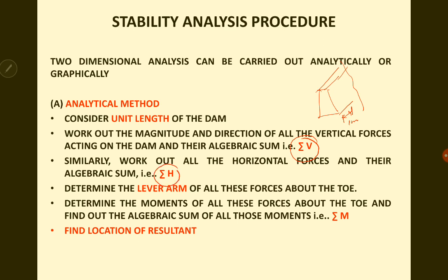Second, find out all the horizontal forces. And then find the lever arm of all these forces. And then determine the moment of these forces about the toe and find out the sigma M value.